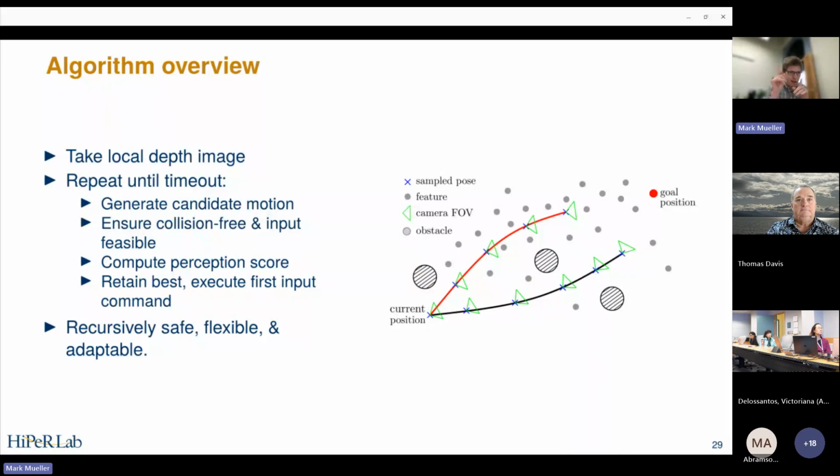But let me just, the trajectories are generated starting from your system's current state. In this context, that's position, velocity, and attitude. And we sample a final state which is in three-dimensional space. And it's at rest, but we sample 4 parameters. So it's the 3D position where you come to rest and the duration that you're allowing the trajectory until it hits that rest. These things, the initial condition and final state and trajectory, fully define a polynomial.